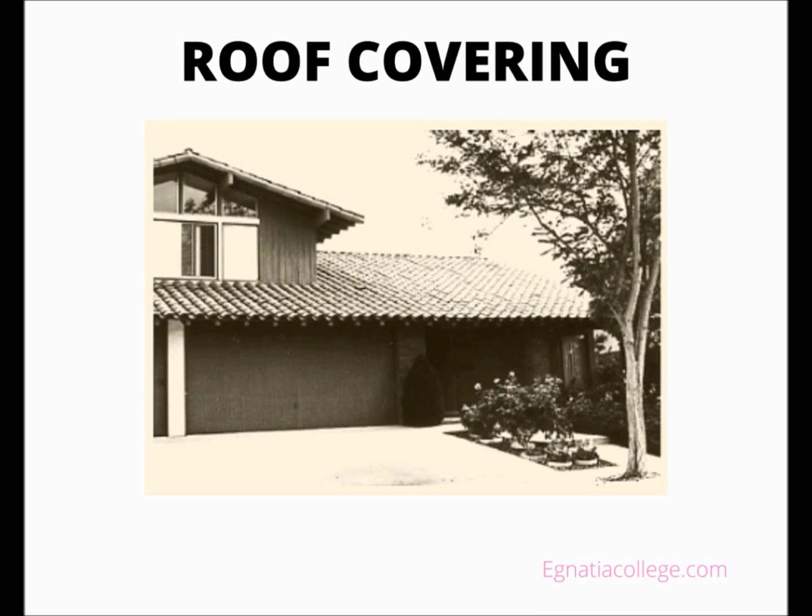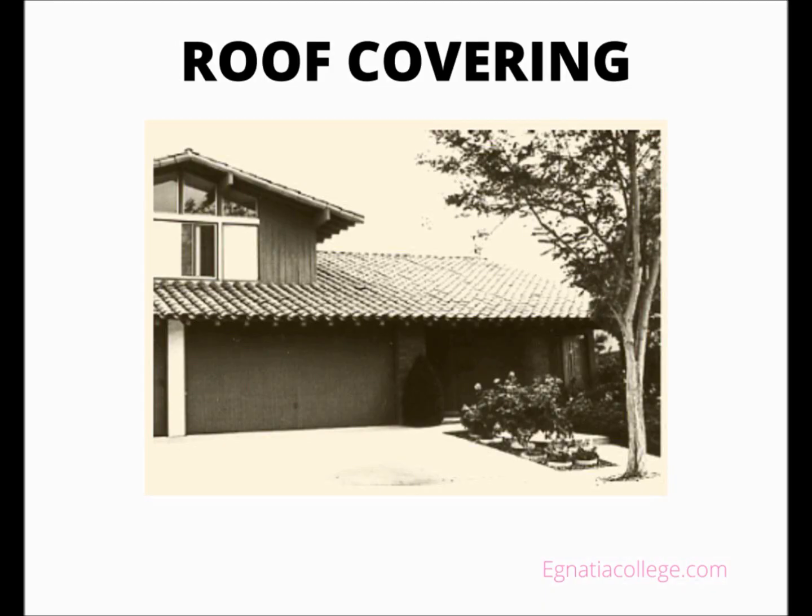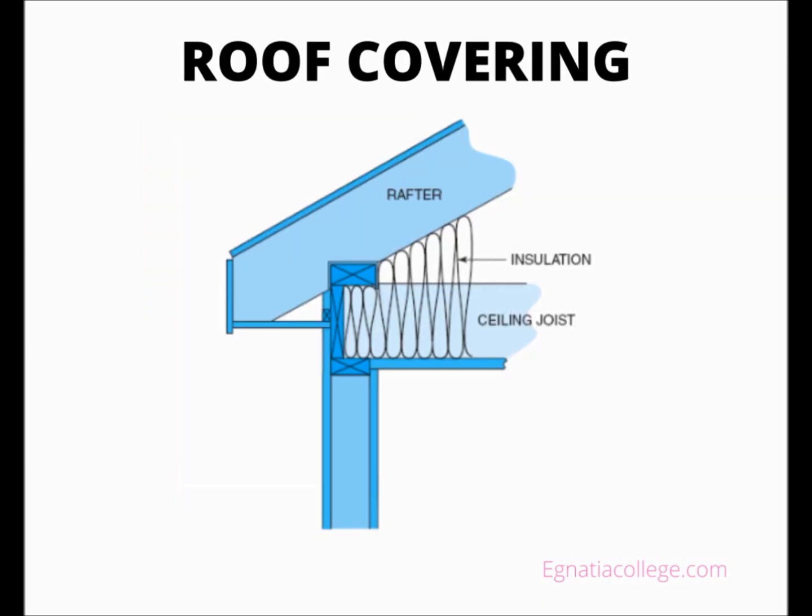The roofing should be applied over a layer of roofing underlayment. The underlayment is a membrane that prevents the chemicals in roofing materials from leaking onto the roof decking. Underlayment also provides an additional layer of waterproofing. There are three types of commonly used roofing underlayment: asphalt saturated felt, rubberized underlayment, and non-bitumen synthetic underlayment, polypropylene or polyethylene.